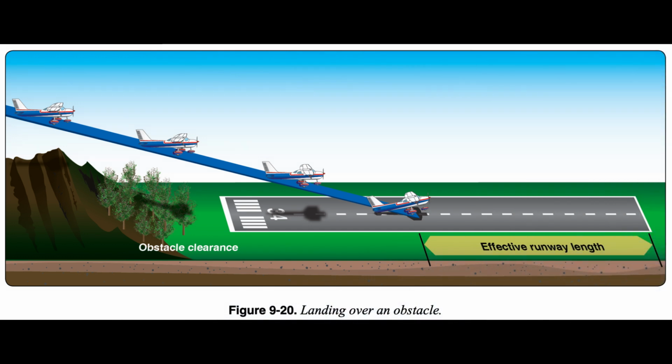Short field approach and landing. Short field approaches and landings require the use of procedures for approaches and landings at fields with a relatively short landing area or where an approach is made over obstacles that limit the available landing area. Figure 9.20 and Figure 9.21. This low-speed type of power-on approach is closely related to the performance of flight near minimum controllable airspeeds.